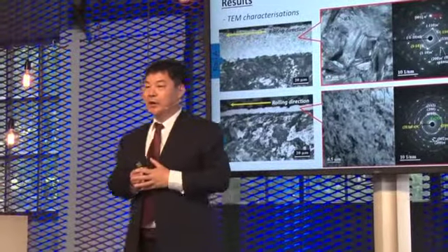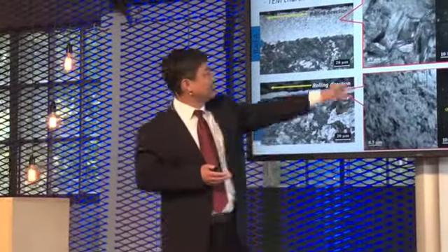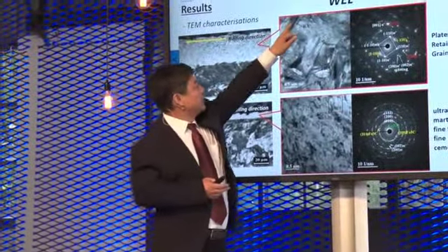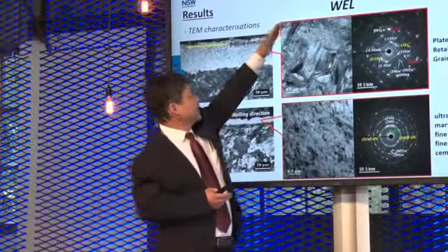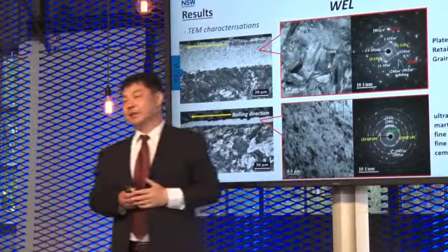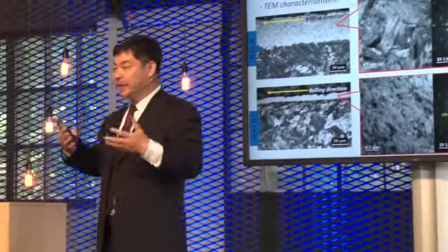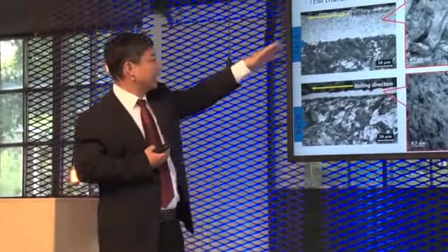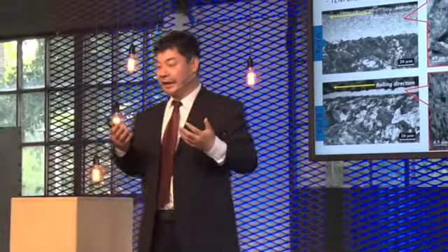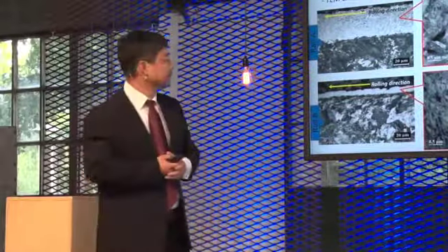One more thing I want you to be careful about. When you observe the retained austenite and plate martensite, you see they are in parallel directions, which means there must be a certain relationship. So the relationship between the retained austenite and martensite indicates a kind of phase transformation.